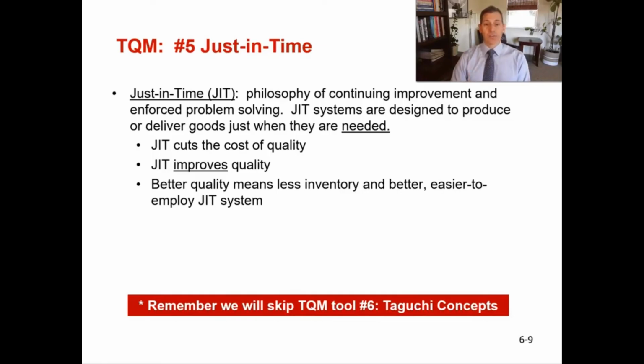Again, just-in-time we will talk about more in Chapter 16 on Lean and Six Sigma. But just-in-time is a philosophy of continually improving and enforced problem solving. So that's the key phrase with JIT. Everyone just thinks of JIT as let's reduce inventory. And that's a big piece of it. But when you reduce inventory, you actually create and uncover problems. So by reducing your inventory, you are literally enforcing problems on your system and on your process.